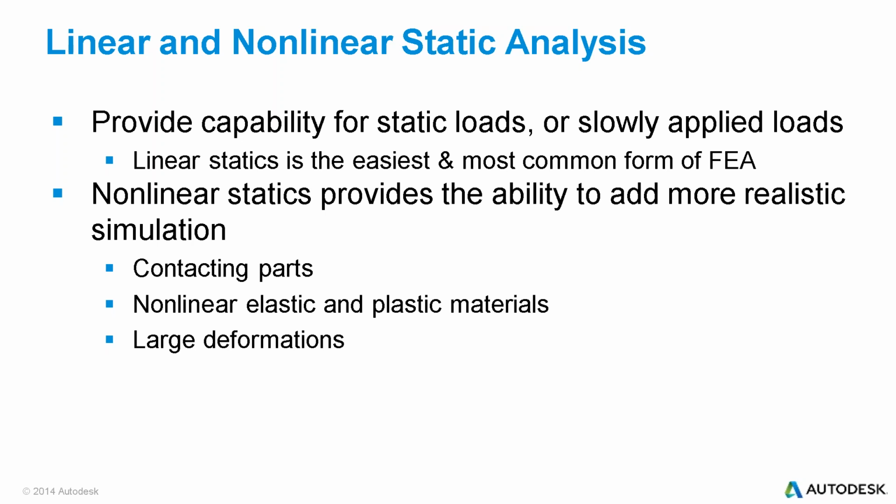And you get the ability to apply a static load, which means the load is applied slowly. It's not a sudden impact load. And that's where the linear portion comes in with your materials and the loading application. That's probably the most common type of FEA that's ran across the board. Is just a linear static analysis.